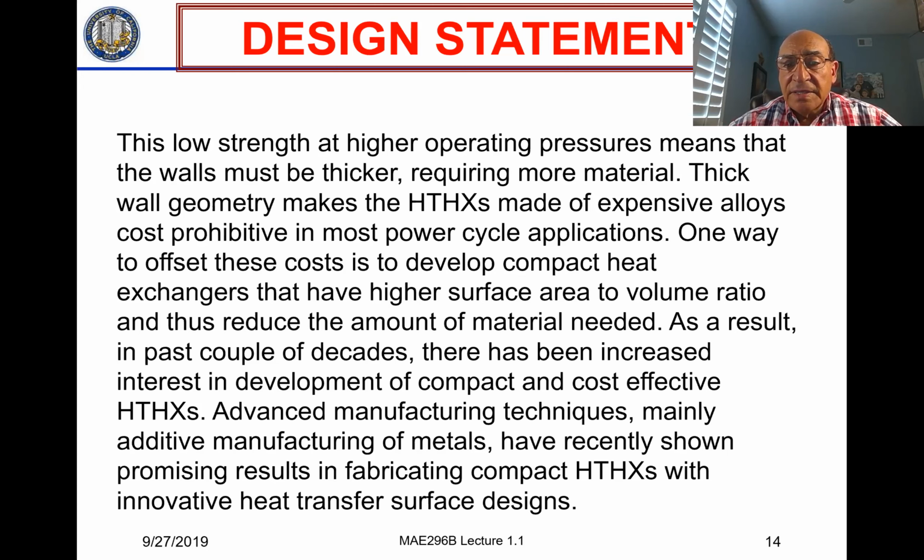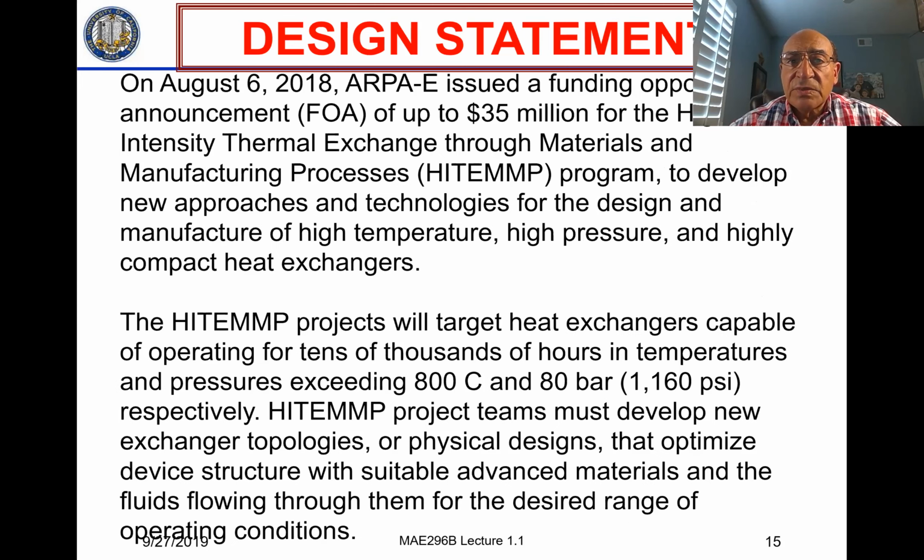So the design constraint is that we would use the announcement by ARPA-E, which was launched last year. So this is a recent announcement where they defined for us the requirements for this ultra high temperature heat exchanger. So we'll take it as a challenge, and then we will do the design where the temperatures exceed 800 degrees C and 80 bars, which is 1100 psi.